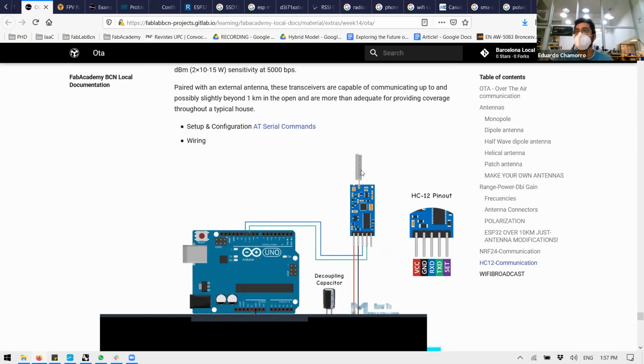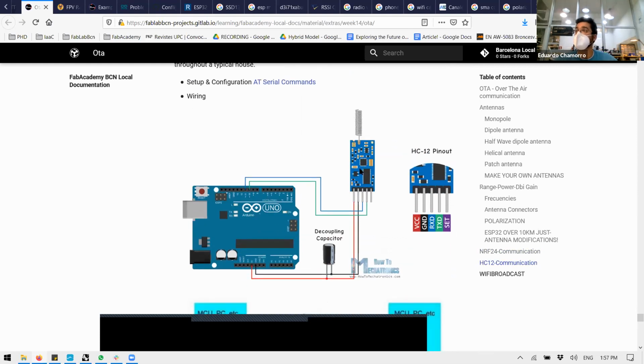Of course, the metal conductivity matters a lot. So for antenna design, you want to use pure copper. If you want to test, we have a box of pure copper cables with different thickness. The thickness also influences the sensitivity. Usually, you want to use as thin as possible.